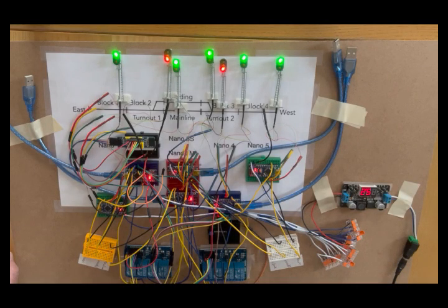With the turnouts here, we have relays that are going to control frog polarity and communications between the Nanos. When we activate a switch here, you're going to see that the LEDs come on when it moves to the siding. Now on a layout, we would be using something like current detection.